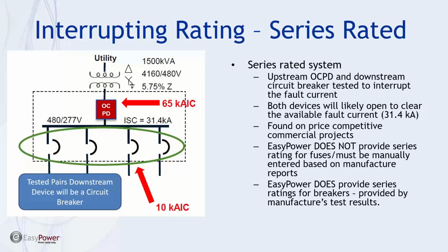When a breaker is used for this upstream device, then that again is going to be a tested pair, if you will, between an upstream device and a feeder device. And EasyPower does provide series rating for breakers, with the admonition that if you change the upstream device type, you potentially may lose that aspect of series rating.